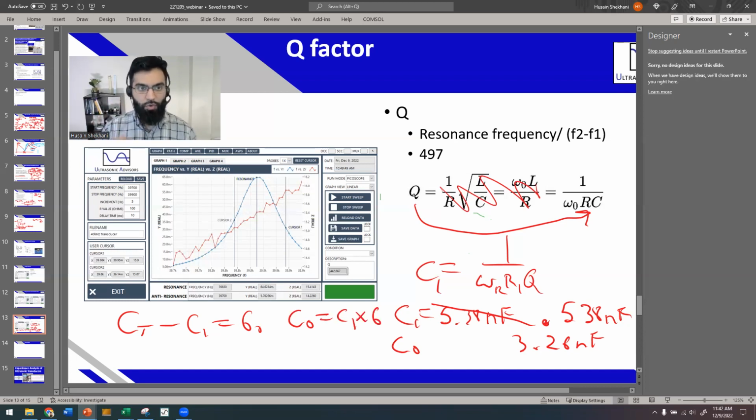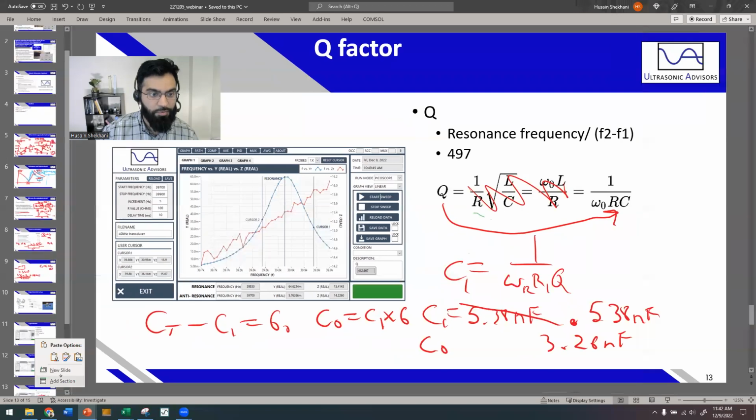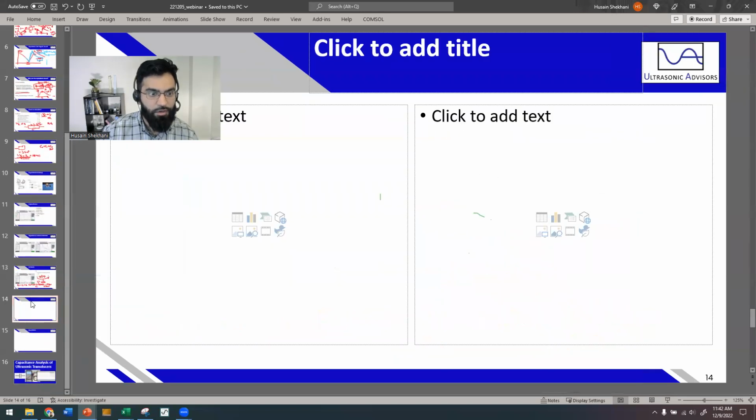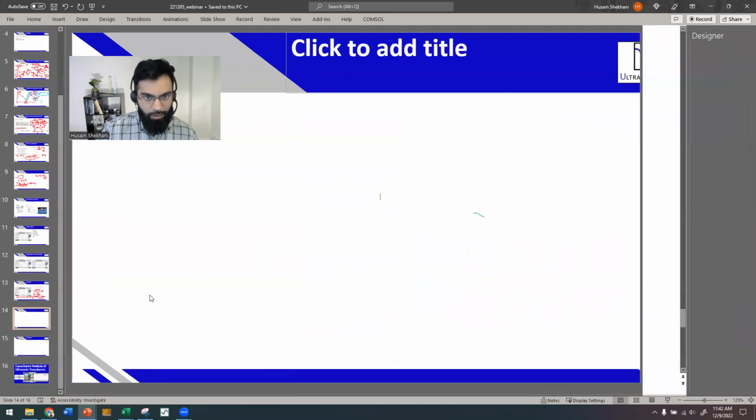So this is necessary. Basically this says when you have this transducer, for off resonance behavior, you might have 6 times more energy stored in the dielectric versus the stored mechanical energy in terms of elastic energy. Oh, this seems interesting. Mechanical and electrical energy ratio. This is going to be really closely related to the coupling factor. So the coupling factor can also be defined from equivalent circuit analysis, which is kind of cool, I think.